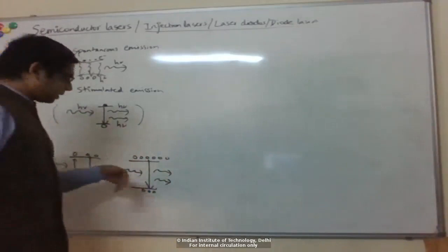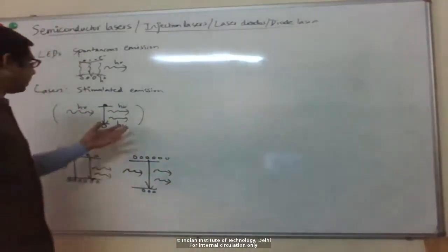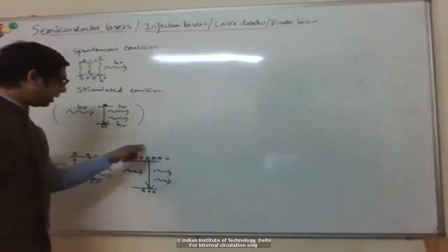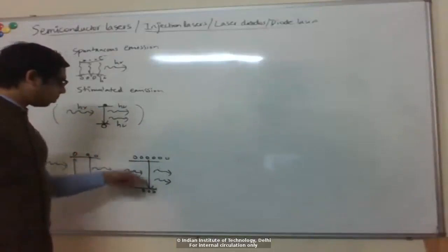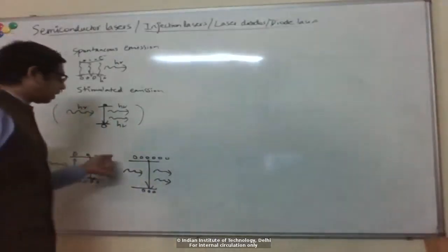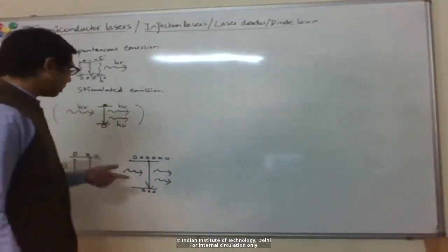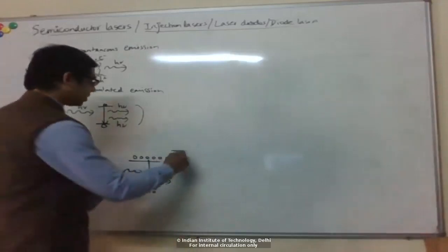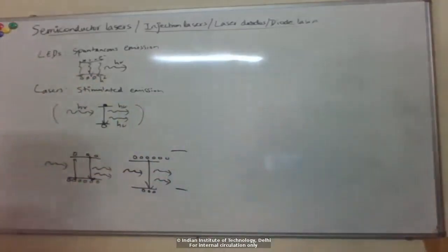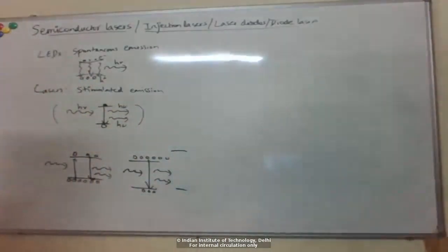So that's the operative principle to make an optical amplifier or a laser: to have some gain medium, and you achieve the gain by having population inversion. There are some tricks that one has to play typically to get this population inversion. You can't, for example, get it in a two-level system. You have to have a third level or four levels sometimes that are used in typical lasers to get this population inversion.